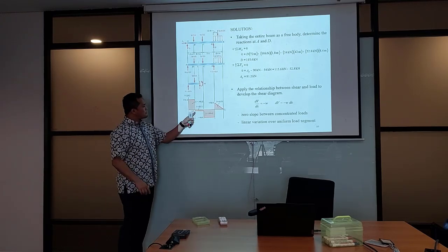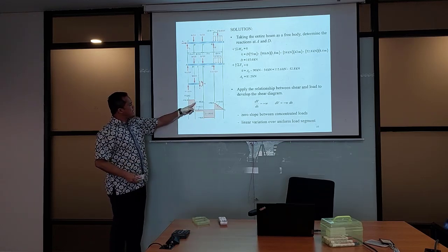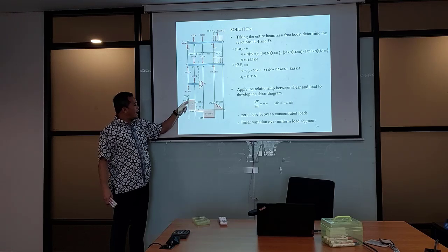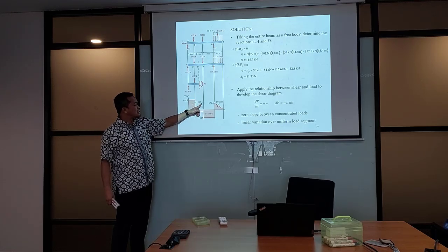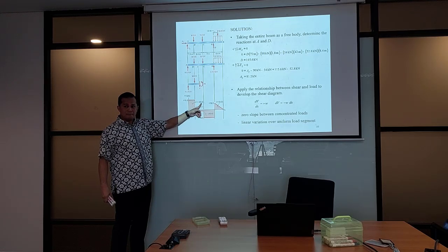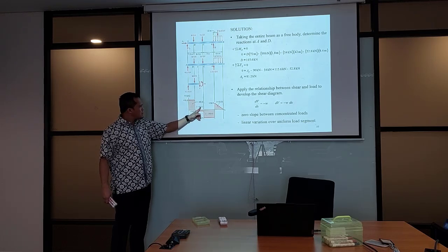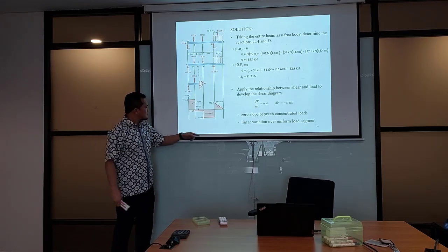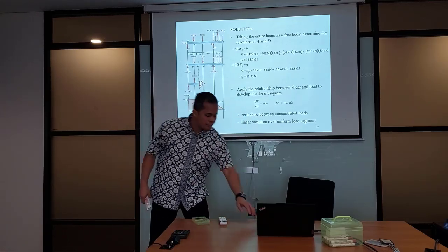Okay, now this one. It is a negative one. So the bending moment, before you look at your BMD directly, you know that it is positive with constant slope, so it will go up and stop at 146.2. After that it should go down because there's a minus 21.1. So 146.2 minus 21.1, you will get 125.1, going downward. Another going downward. So the BMD will look like this.